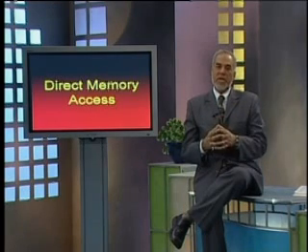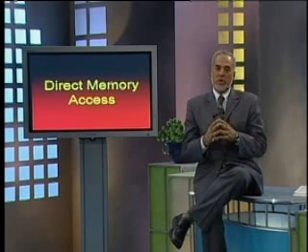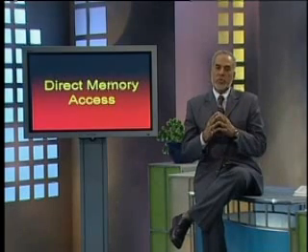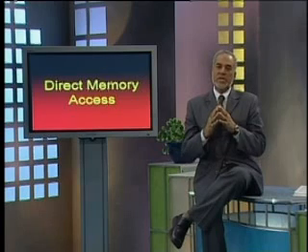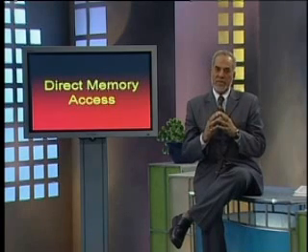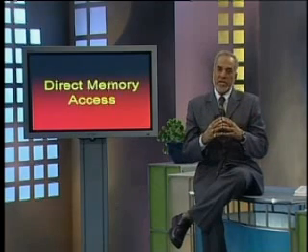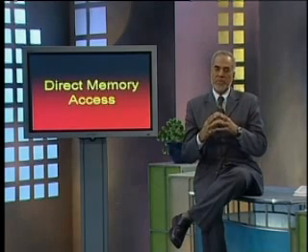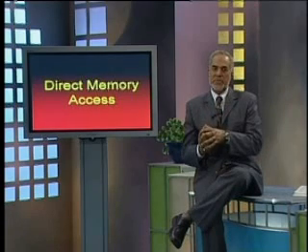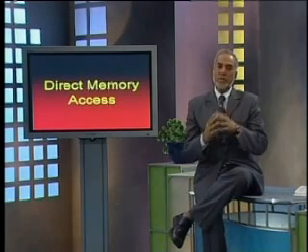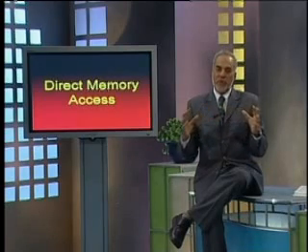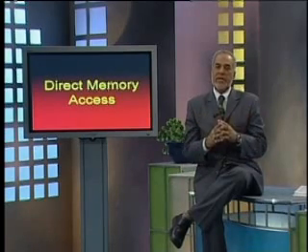The transfer rate is pretty fast, and conceptually you could imagine that through disabling the tri-state buffers, the system bus is isolated and a direct connection is established between the I/O subsystem and or the memory subsystem. And then the CPU is free, it is idle at that time, or it could do some other activity.